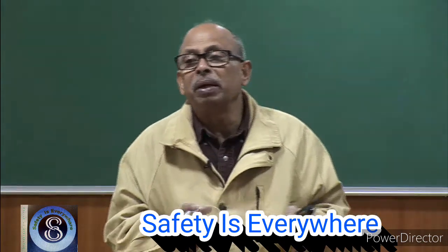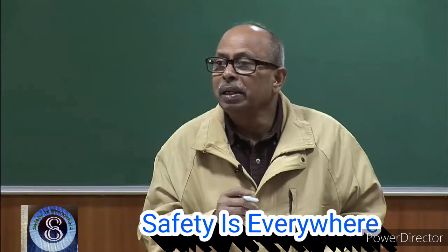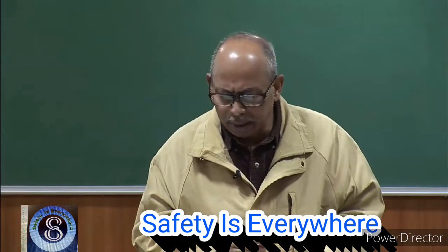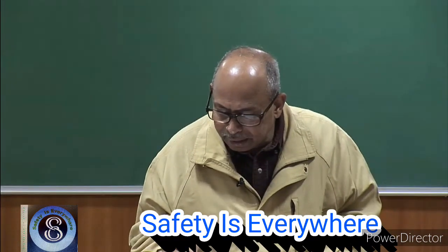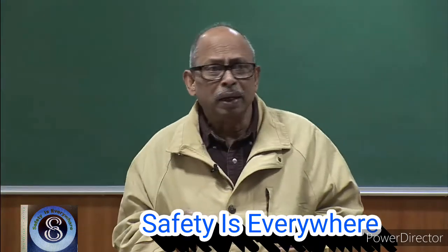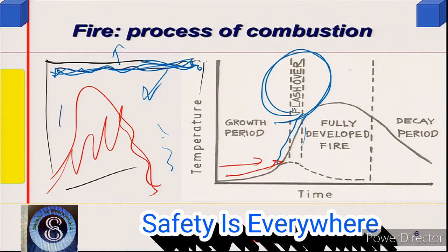More or less you will have some kind of uniform temperature in the whole room, and a time will come when the whole room will attain the ignition temperature of the combustibles, which on average will be similar. Suddenly you find there is an increase in temperature. The point where this occurs, we call it flashover. This terminology is used in some other places also, fire related or wherever. So there is a flashover point. Flashover means everything now has caught fire.